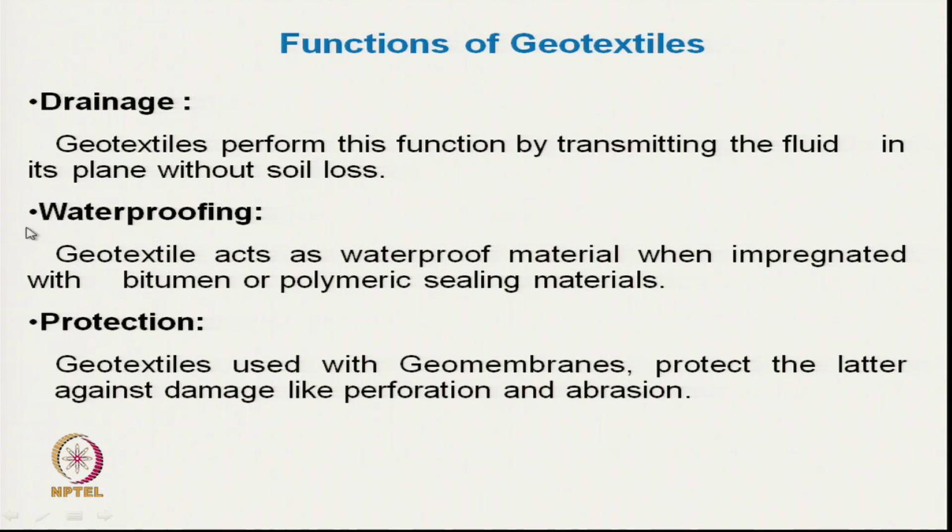Waterproofing is required for some specific purpose, when the geotextile is impregnated with bitumen or polymeric sealing material. Protection is a function where geotextile is used for protecting the geomembrane, because geomembrane is used for preventing the seepage.